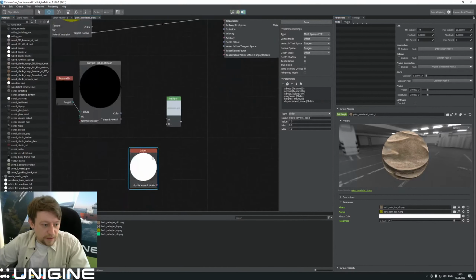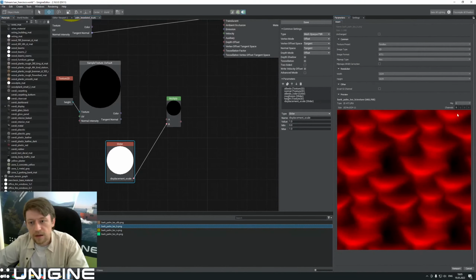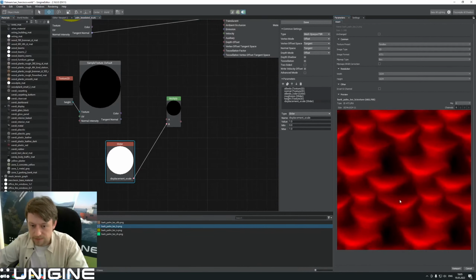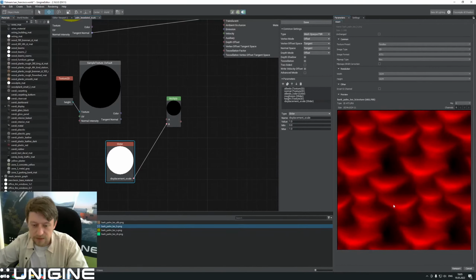and multiply it with the X component of the texture, because I know that I have one single channel texture here, which is actually normalized. Height maps should always be normalized, so they need to contain a whole spectrum of the values from 0 to 1.